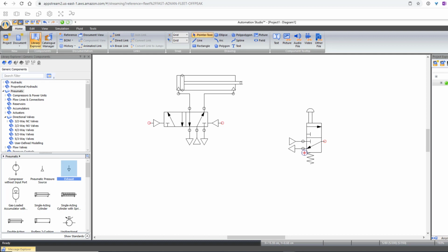Now, put your valve numbers in here, your port numbers. You've got your port numbers in, you've got this actual push button labeled, indicating what it does. So you can say extension and retraction, whatever you want. Watch this, you'll love this. Select the whole thing, plus the text on top, Control C, Control V, and all of a sudden you've got it all over again. And just change your text up here that says extension to retraction, or whatever you typed in. Now, I'm going to grab this guy and put him over here.